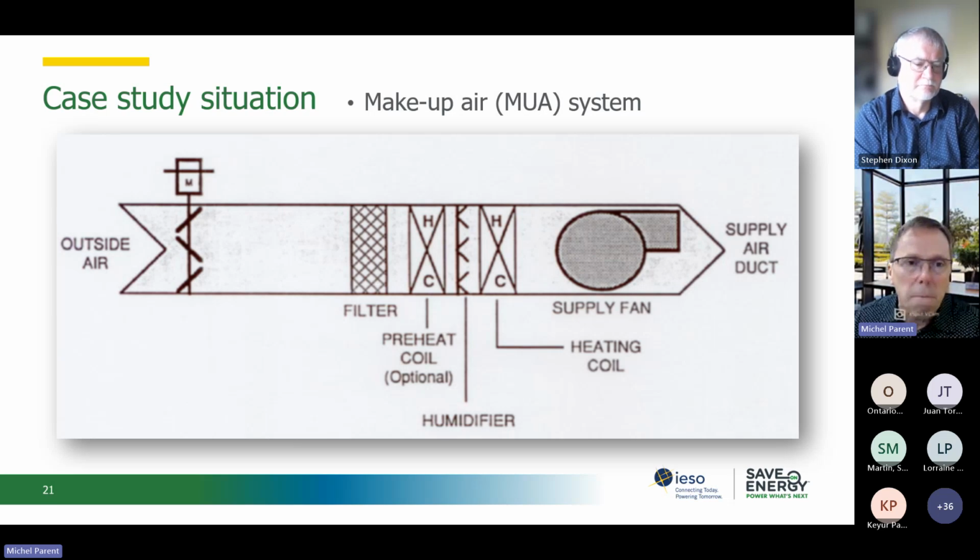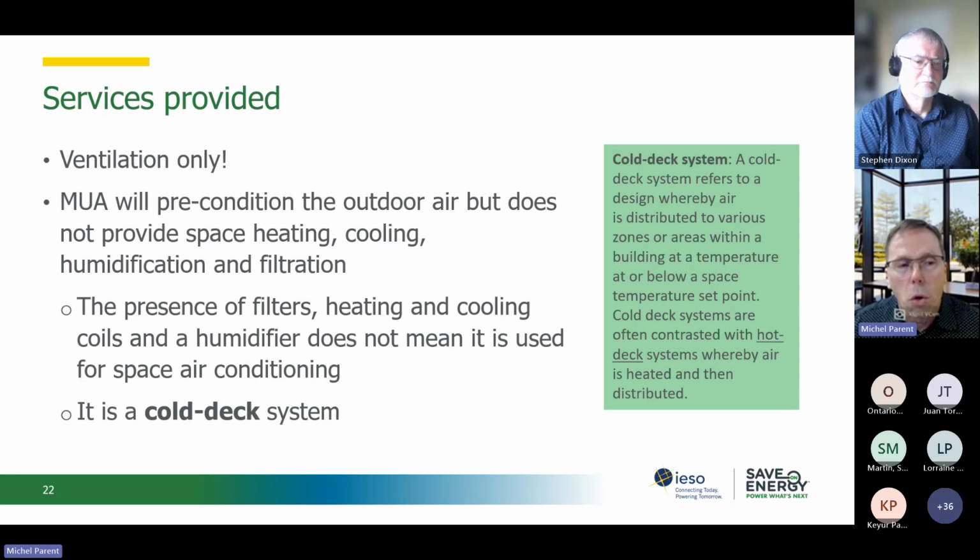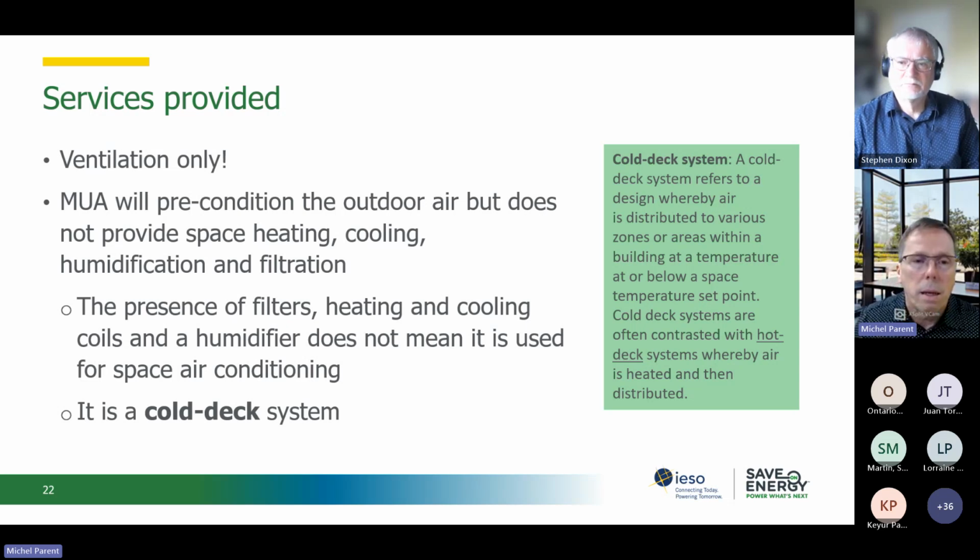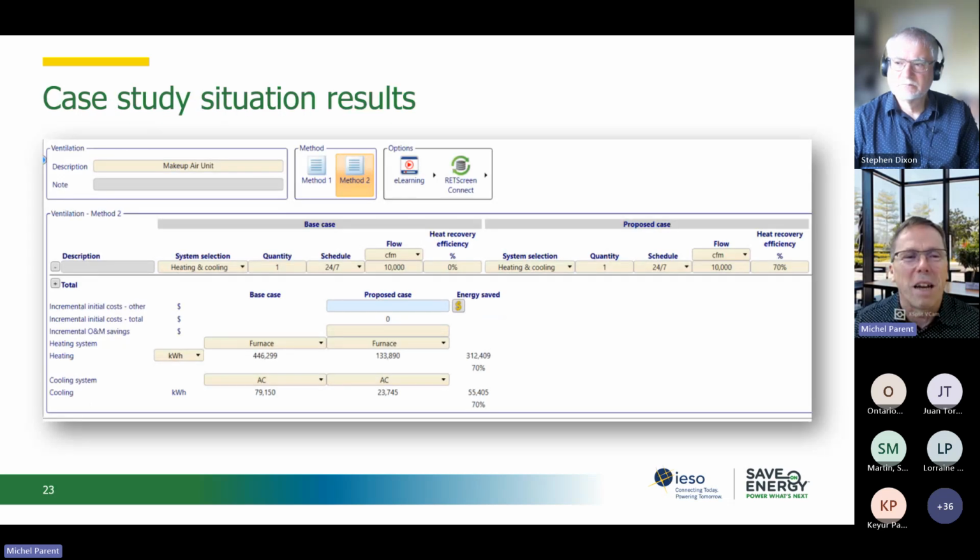So if you have a system that is controlled by a supply duct sensor, you will have to model it differently than you would do with the single zone system that we saw in RETScreen. So that's actually, again, I cannot underline enough how important it is for you to understand if you have a cold deck system, so a system controlled by a supply temperature sensor. And again, there are exceptions where you do have a temperature sensor in the supply duct and it's a switchover system, but I'm not going to go there, Stephen. I know probably I'm going too far already.